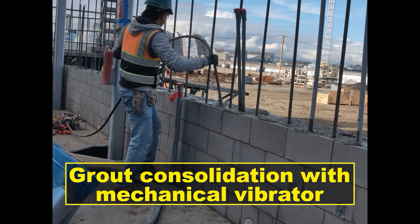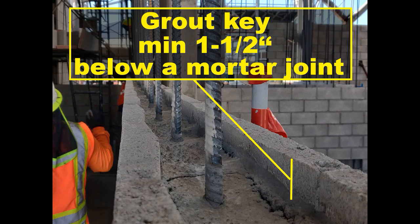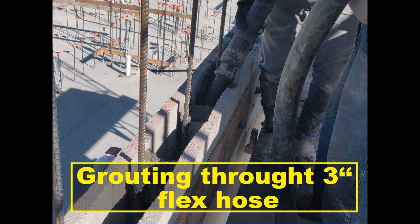Apply vibrators at uniformly spaced points not further apart than the visible effectiveness of the machine. Limit duration of vibration to time necessary to produce satisfactory consolidation without causing segregation. If previous lift is not permitted to set, dip vibrator into previous lift. Do not insert vibrators into lower lifts that are in a semi-solidified state. If lower lift sets prior to placement of subsequent lift, form a grout key by terminating grout a minimum of 1.5 inch below a mortar joint. Vibrate each vertical cell containing reinforcement in partially grouted masonry. Do not form grout keys within beams.